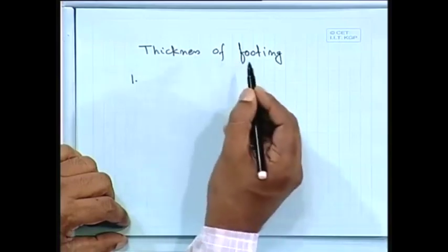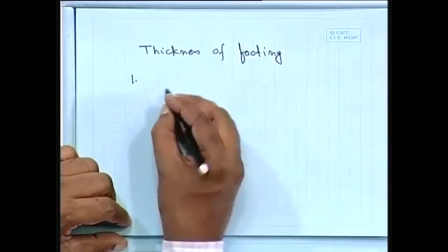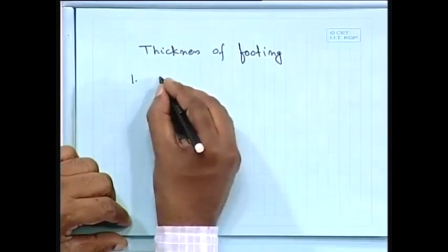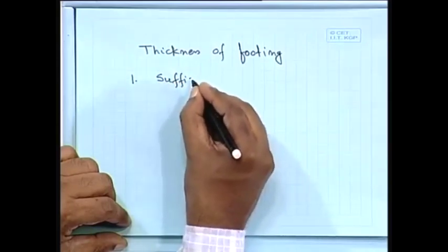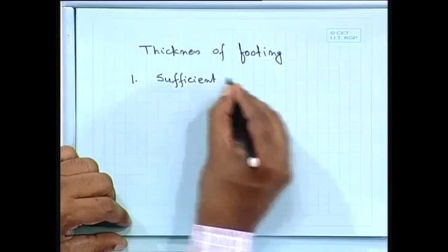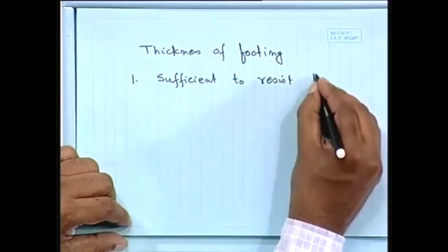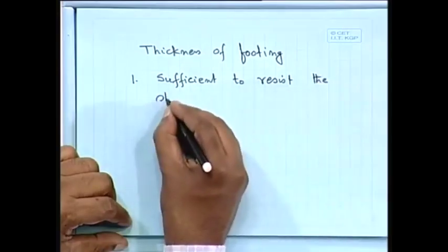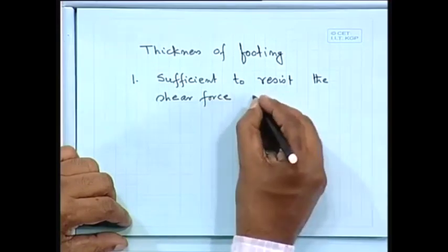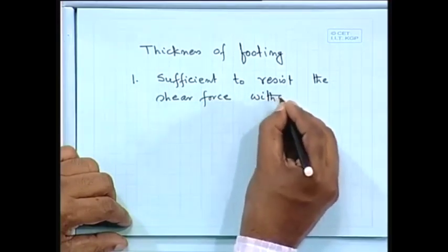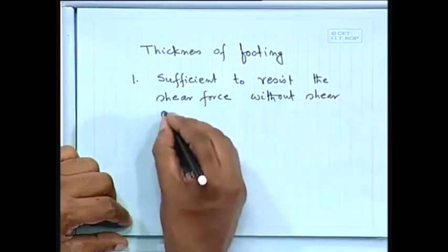What should be the thickness of footing? How shall we, what is the governing criteria? It should be sufficient to resist the shear force without shear steel.